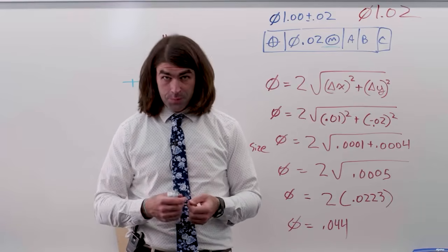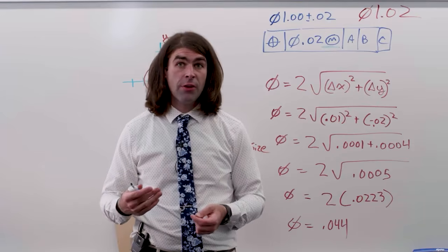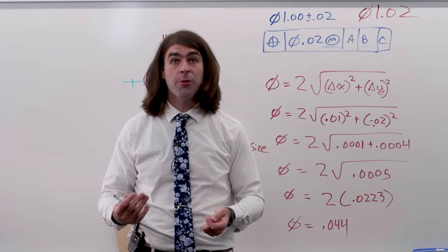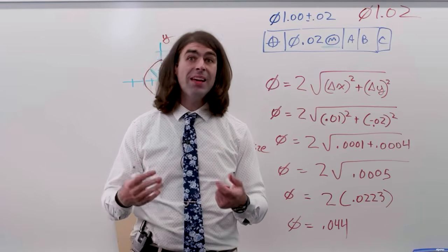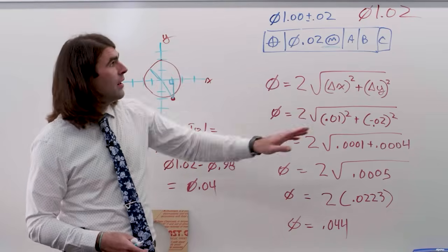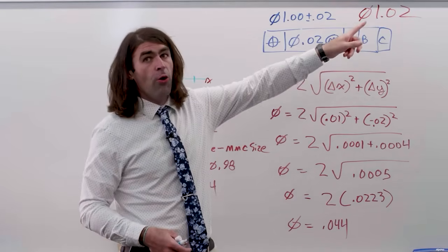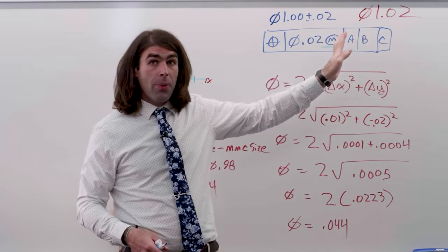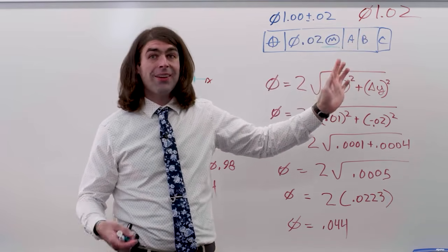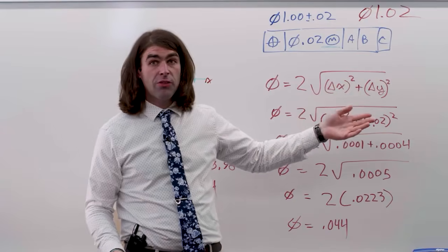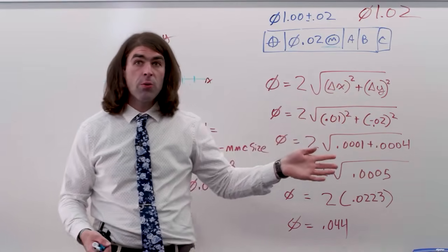If you're lucky, the same gauge pin will fit in every single one, but if you're inspecting, it's something you want to keep track of. Okay, so that's how MMC can help you. Say we checked the part and the hole came in small, you could go back and drill or bore that hole out again and then send it back to inspection. So it gives you the capability for rework.